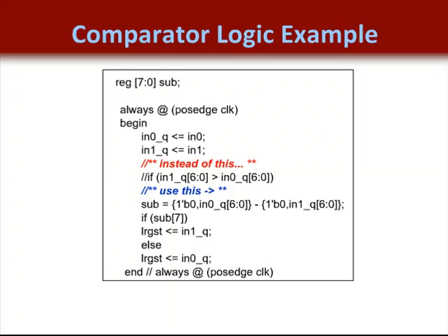In this implementation, a subtraction was used instead of a LUT implementation. As we mentioned, the benefit is that the carry chain is used and improves the speed of the comparator. As you can see, the greater than and less than signs are too ambiguous since they have to check for all possible conditions. This implies a lot of combinatorial logic since we are comparing two 7-bit buses in this example.